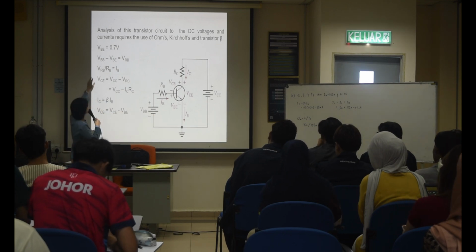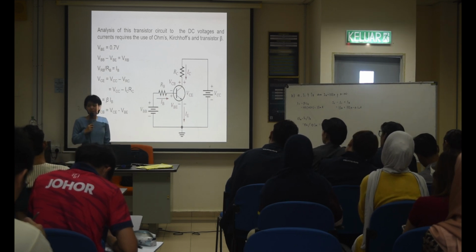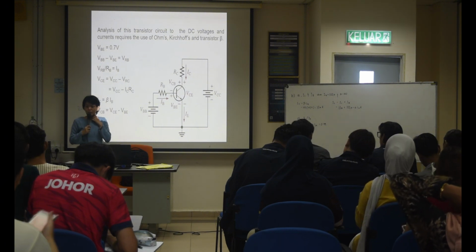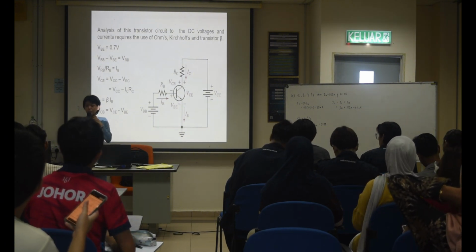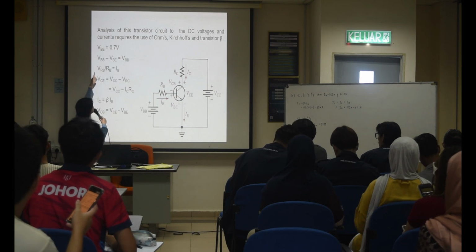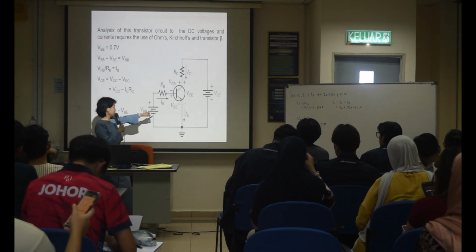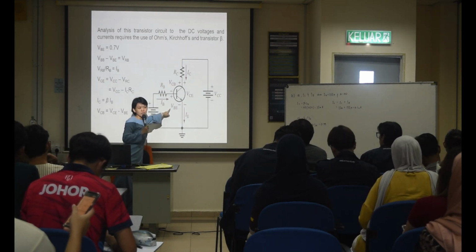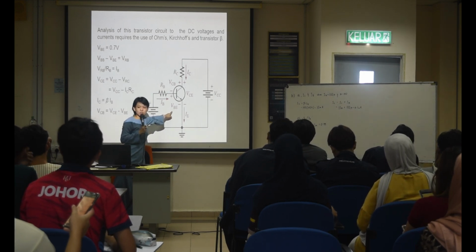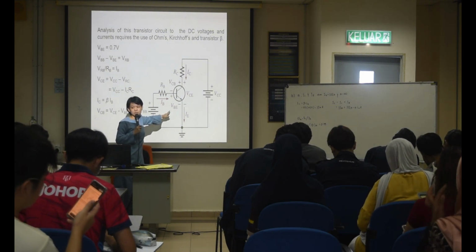Remember this one, okay. First, we know voltage bias, right? Do you remember voltage bias? Diode for voltage bias, correct? How much voltage bias for a diode? 0.7. So first, VBE is 0.7. This one is always fixed. If the question gives you a value, then you use the question's value. If the question doesn't give you, you use 0.7.